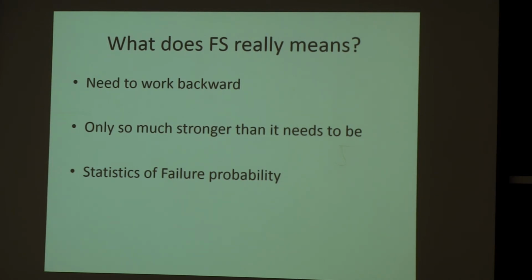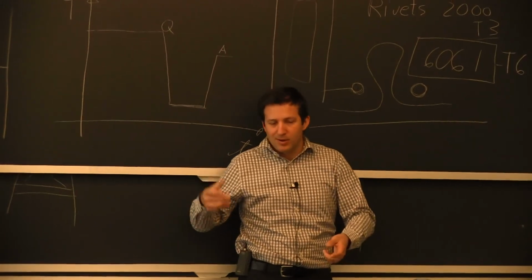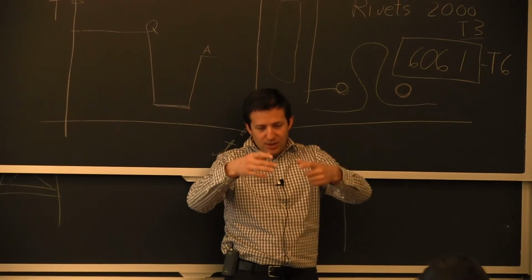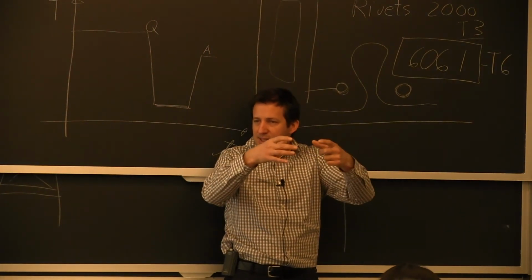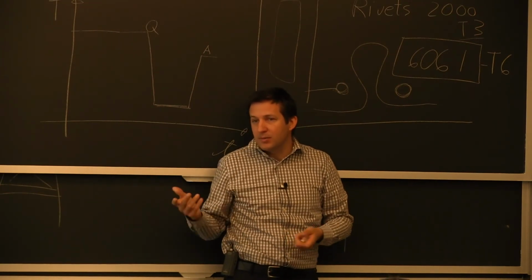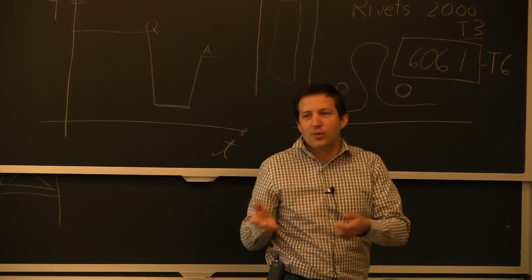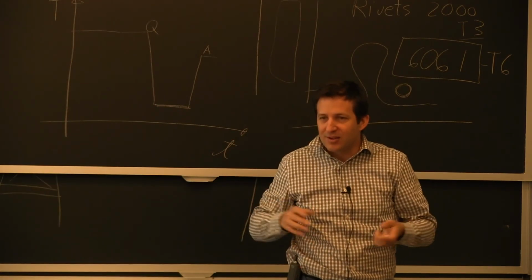Are you going to put in ground settlement on the bridge, which can affect a lot of the stress distribution? If you have one pier that just doesn't have a foundation as stable as the other, it's going down. And that happens on the Longfellow Bridge right here, for example. And how do you deal with it? Does it affect the overload on some of these main truss structures?